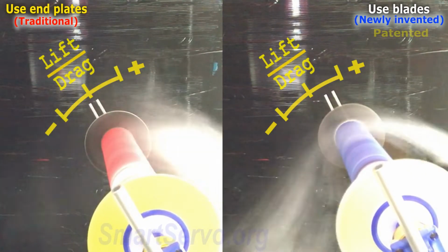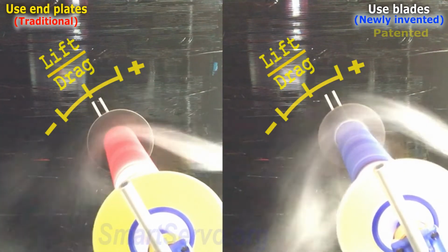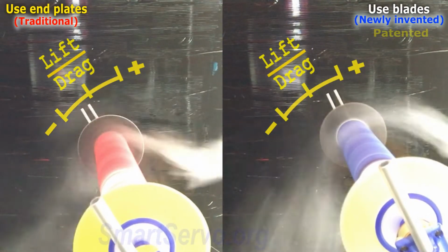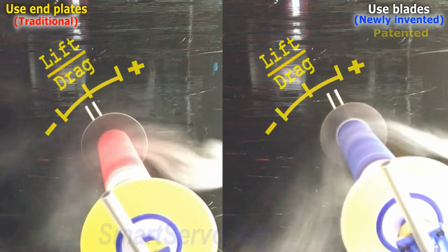As the smoke gets closer to the rotor, the more curved the path. Therefore, the centripetal force exerted by the blue rotor on the airflow is larger, and the reaction force causes lift. This may be why the blue rotor could also produce more lift.